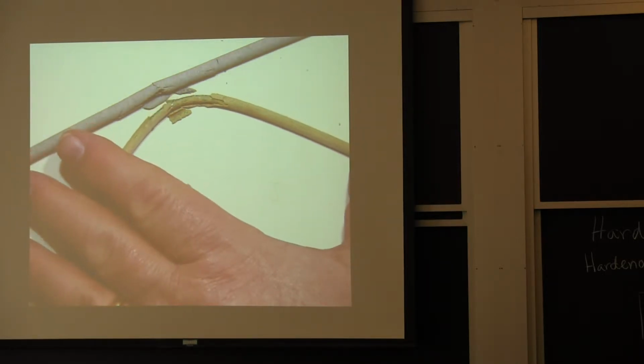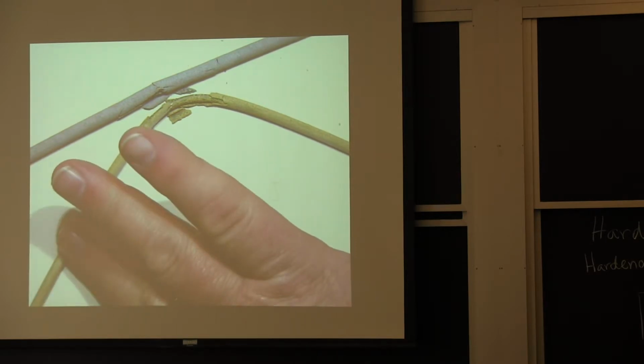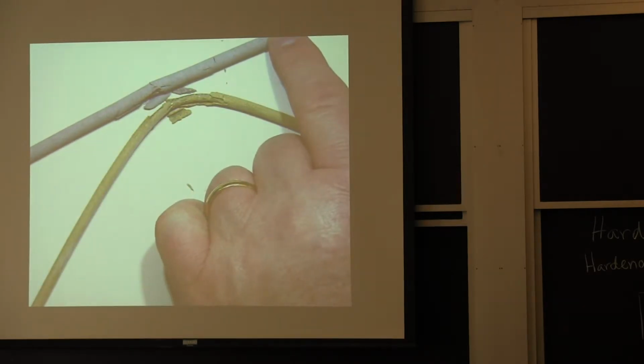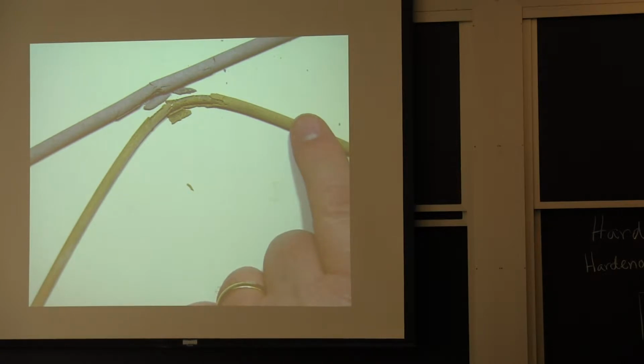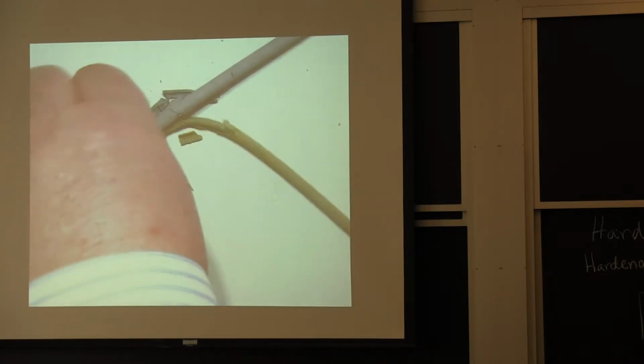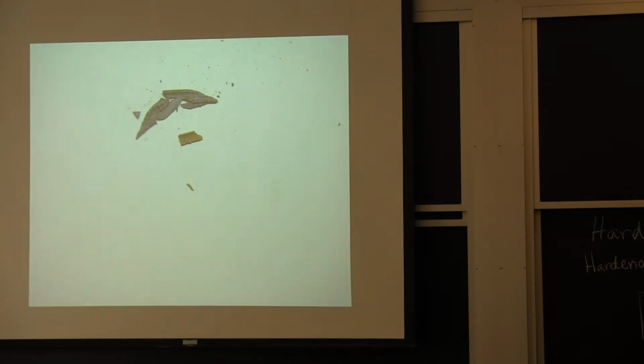But in any case, the 7018 is baked at around 400. This one's baked about 750. There's less moisture in the 7018. The 7018 is known as a low hydrogen electrode. The 6011 is a normal electrode, or high hydrogen. We don't usually call it high hydrogen. We call the ones that are low hydrogen, low hydrogen. Okay, so in any case, we have different types of electrodes because that controls part of the moisture.